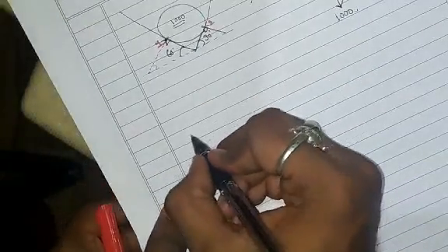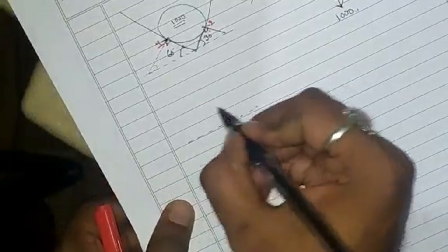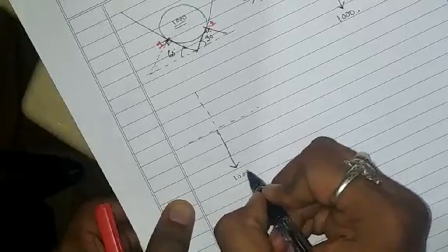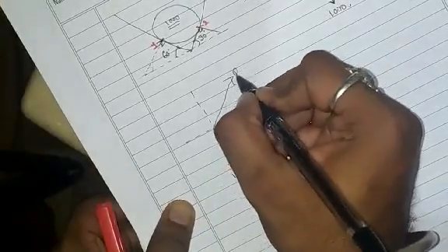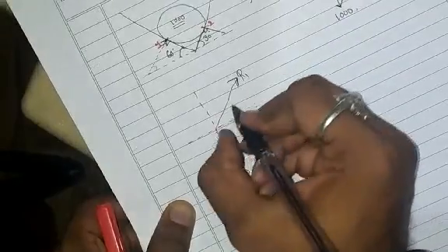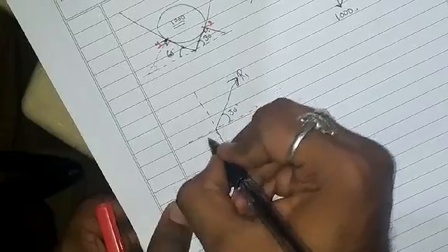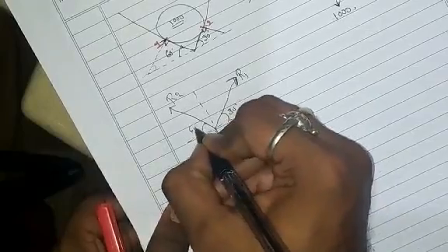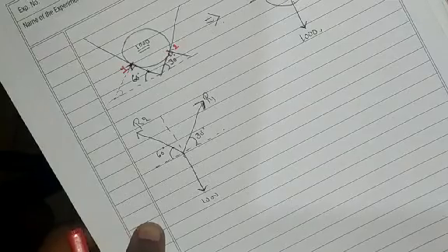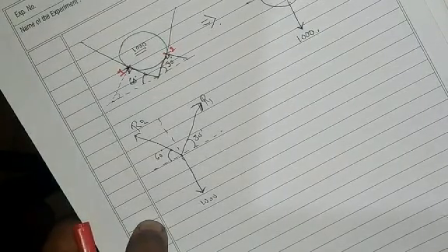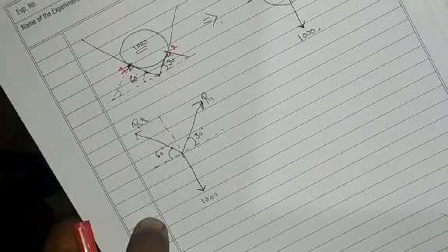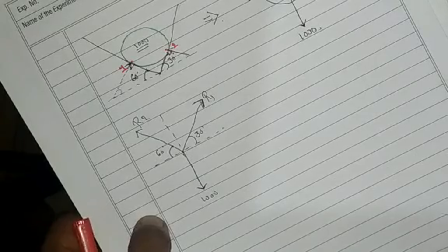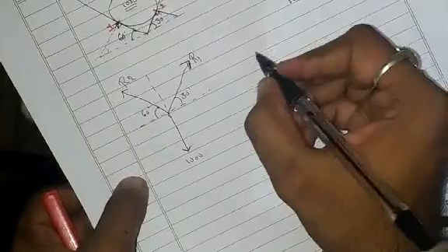If you redraw the coordinate system, let it be your x-axis, let this be your y-axis. Here this is 1000, here this is your R1. R1 is at an angle of 30 degrees with horizontal, and let it be your R2. The angle is 60 with horizontal. As there are only three forces, you can use Lami's theorem. If you don't want to use Lami's theorem, apply equations of equilibrium, that is summation of horizontal forces is equal to 0 or summation of x equal to 0, and summation of vertical forces is equal to 0 or summation of y equal to 0. I am using Lami's theorem here.